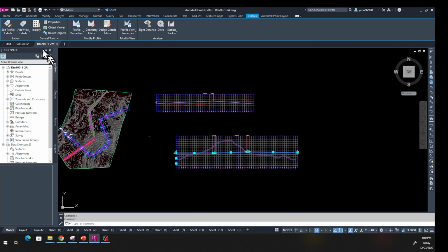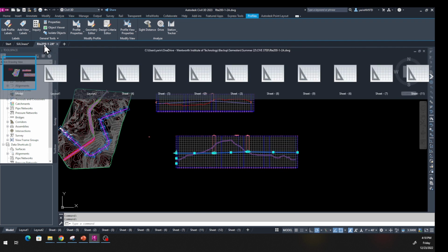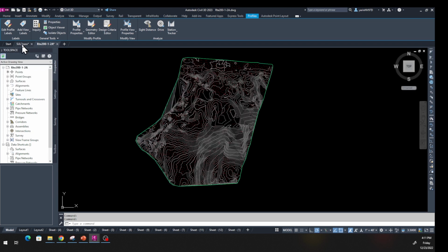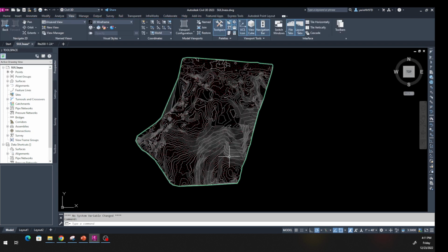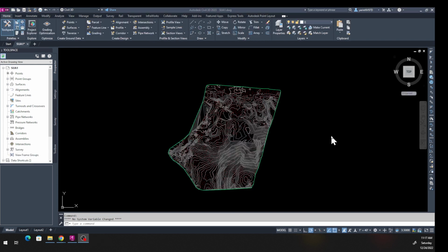So before you go ahead and work, why don't you download this. If you've been following my series of tutorials, you should have this already. But if you don't have it, down below in the description, download this file. We will use this. Before we create a profile of this surface, let's create a quick alignment, and then we're going to take that alignment and create a profile from there.